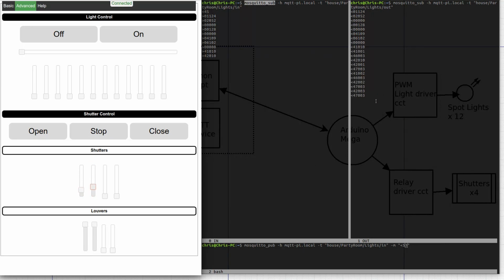It knows what control voltages are being applied to it and where they actually are. Everything is incremented in 10-degree steps. So we can see here, this is a full shutter running from the floor to the ceiling, and this is a window shutter, so it's a lot faster. And the information being replied back is the location of the actual shutter itself and the louver information. So there's 2 returned bytes per shutter.